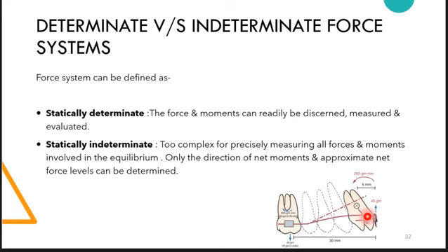When there is no couple at the other end, it is called a one couple system. This means that a wire that will serve as a spring can be inserted into a tube or a bracket at one end, but must be tied so that there is only one point of contact on the other. When the wire is tied into a bracket on both ends, a statically indeterminate two couple system has been created.